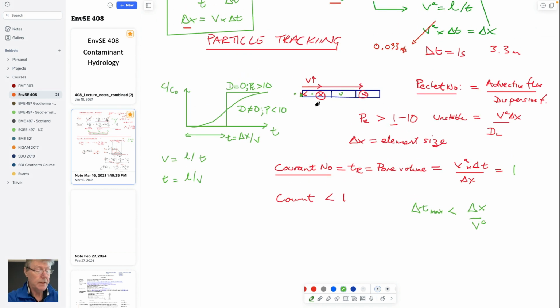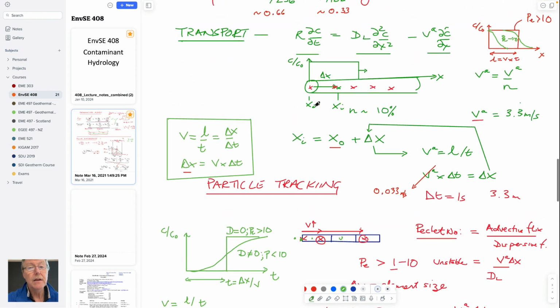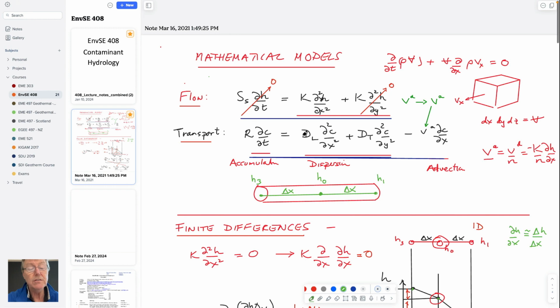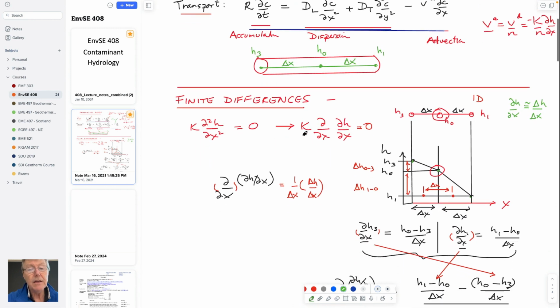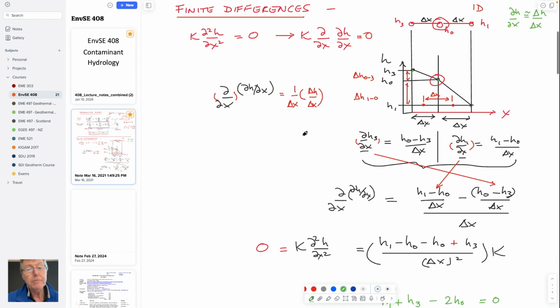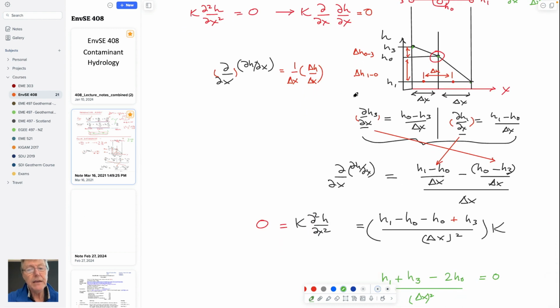So that's it. That's all that these numerical models do. They take these somewhat complex partial differential equations. They can represent them as finite differences quite easily. Hopefully you can represent what the finite differentials mean in terms of just these head values as you go downstream, both in terms of a first order PDE defined at each of these nodes, and then a second order PDE, which is just the change in the first orders between the upstream and downstream.